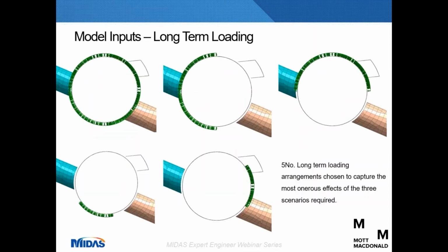So given that leads us to infinite possible arrangements of this radial load, we came up with a limited number to apply in the modelling, which we considered to produce the worst case forces in the primary lining. And these 5 arrangements are shown here. These are snapshots from the model with the radial load application shown in green. So one scenario with it all the way around, 2 half loading scenarios, and then 2 where it's just applied over specific 65-degree zones.